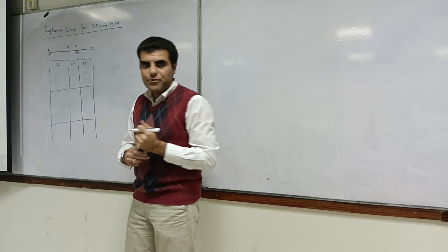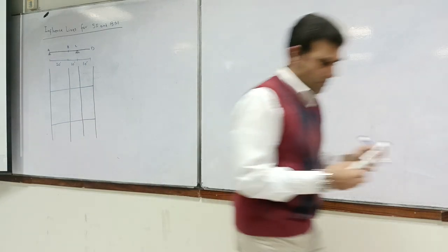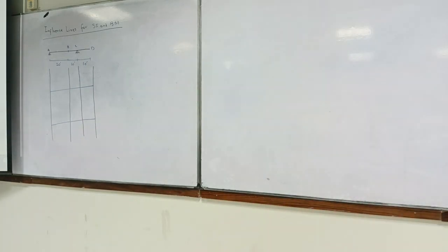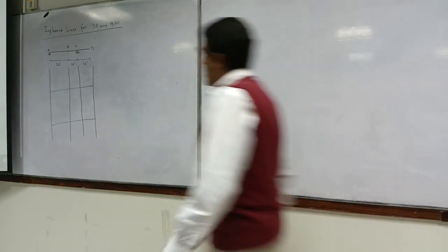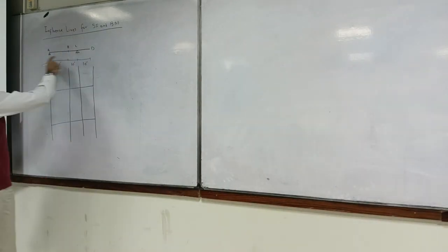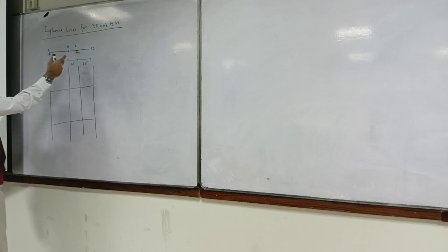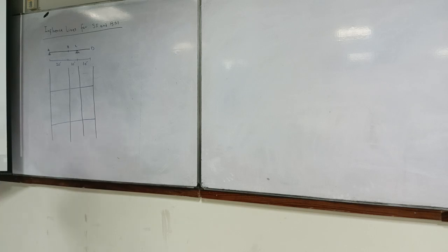Okay, let's draw the shear force diagram for this one. Sir, there is a pin and a... No, there is no pin. Yeah, this is pin support. But it doesn't matter whether it's roller or pin, because your load is always vertical.